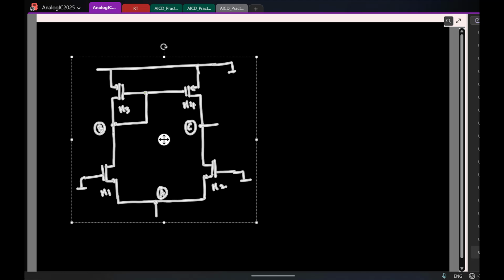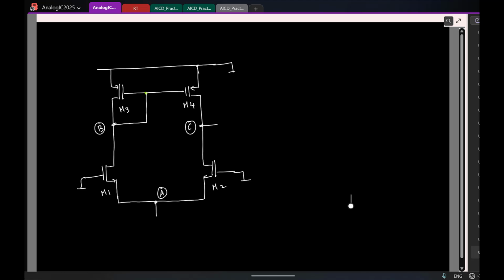Great. So we are now interested to find the resistance looking into the node B. So once again, what will I do? Yeah, same thing, test voltage and find the test current. This is V-test and I'll find how much is the current drawn.